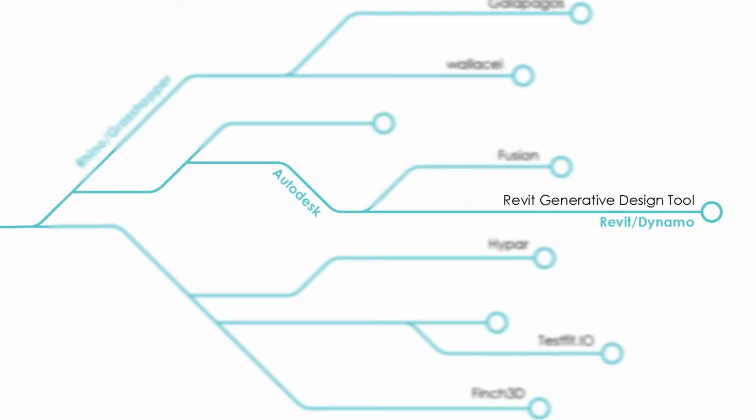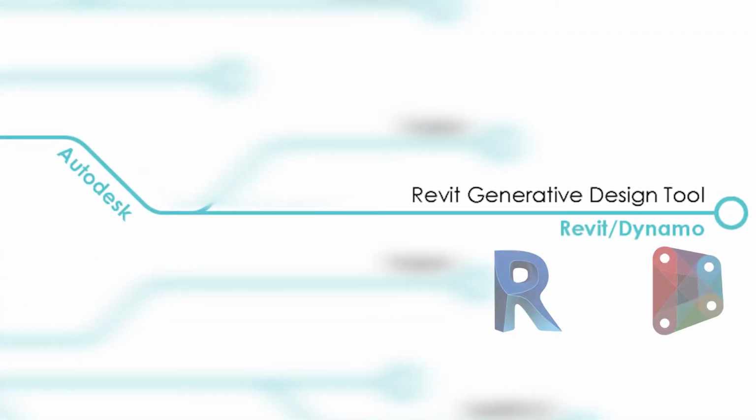If you look at Autodesk, the same way Dynamo is to Autodesk Revit, it's the same way Grasshopper behaves with Rhino. So Dynamo is really the code where you're setting up your ingredients and what the inputs and outputs are, but the generative design tool is pretty much an evolutionary solver that uses a genetic algorithm to run through all the inputs in your Dynamo script. So what it actually does is it opens Dynamo quite a few times on different threads on your computer, and it runs that script with different inputs basically.